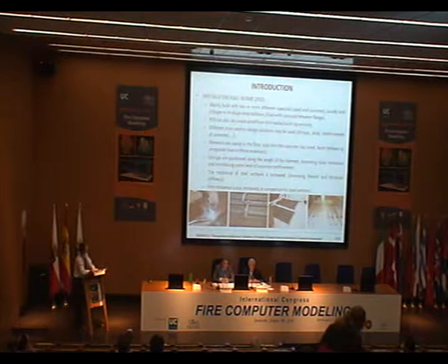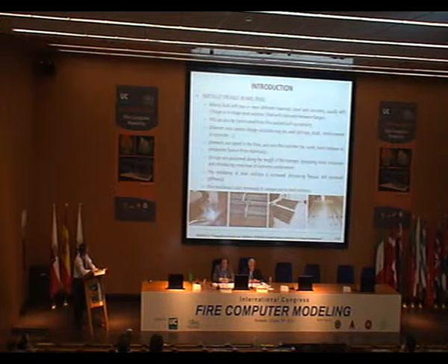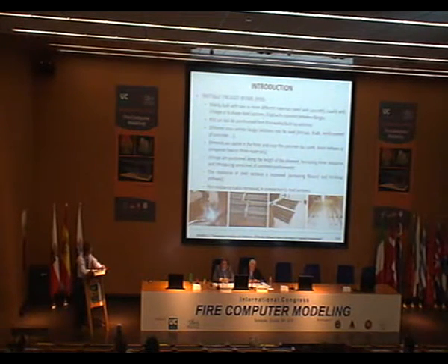And the elements were cast on the floor, and once the concrete has cured, the beam is a composite, meaning 2 or 3 materials, and the stirrups were positioned along the length of the beam, as you can see here, in the preparation of the specimens, and the resistance of the steel section is increased doing this. So we expect to increase the stiffness of the element, and also an important characteristic is that we increase the fire resistance of the elements.